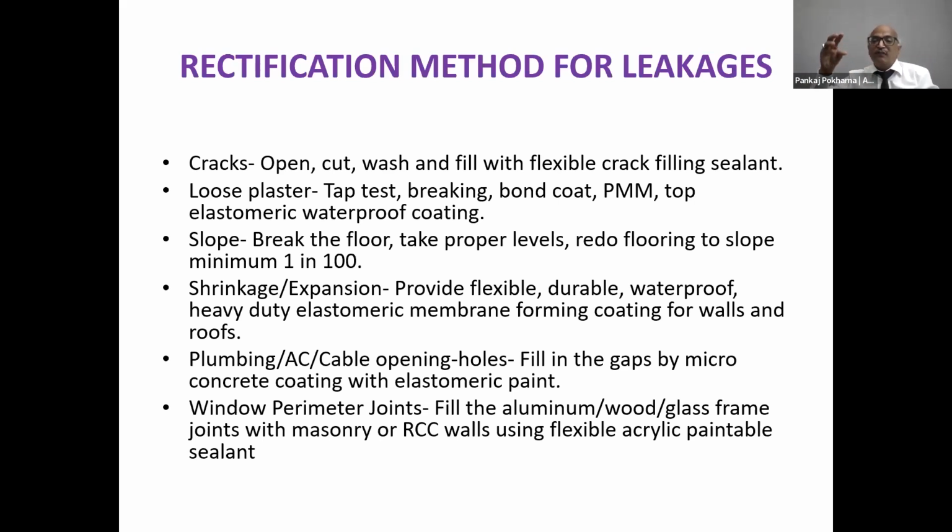All these areas, if you repair with normal plaster, will re-crack. So all these areas should be repaired with a special concrete known as micro concrete, which is free flowable. You have to clean that area with an air blower, remove the loose dust, apply a polymer bond coat, and then pour or fill with micro concrete. This micro concrete is a free flow, self-compacting mortar which will penetrate into the micro areas and seal it from inside. And because of the non-shrink property, it will not shrink and crack much.